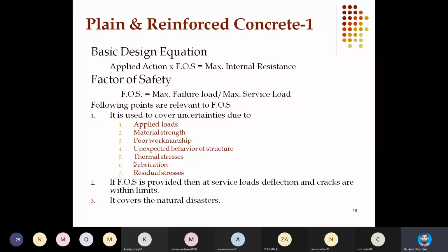So that is the reserve capacity, that if the structure is loaded further, additional load will be applied, and the design load of 500 kg per meter square dead is increased to 600 kg per meter square dead, which was used in the calculation, and rather than 200 kg per meter square of live, they increased it to 400 kg per meter square.